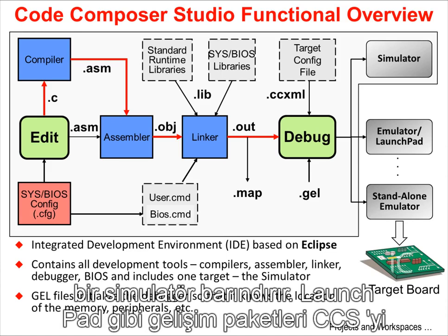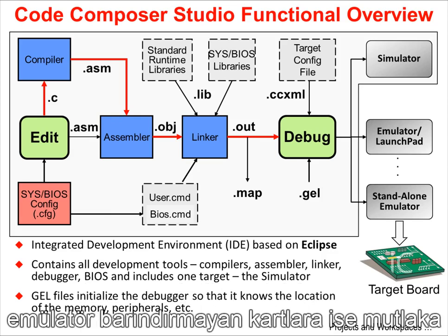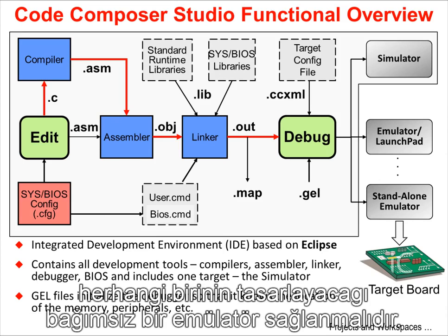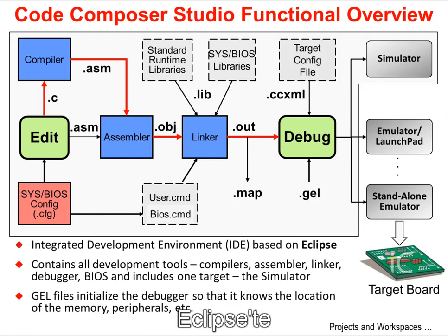Evaluation boards like the LaunchPad contain their own built-in emulator to connect CCS to the hardware. For target boards that do not contain an emulator, like any normal customer design, a standalone emulator must be provided. There are many available from TI and other third parties.